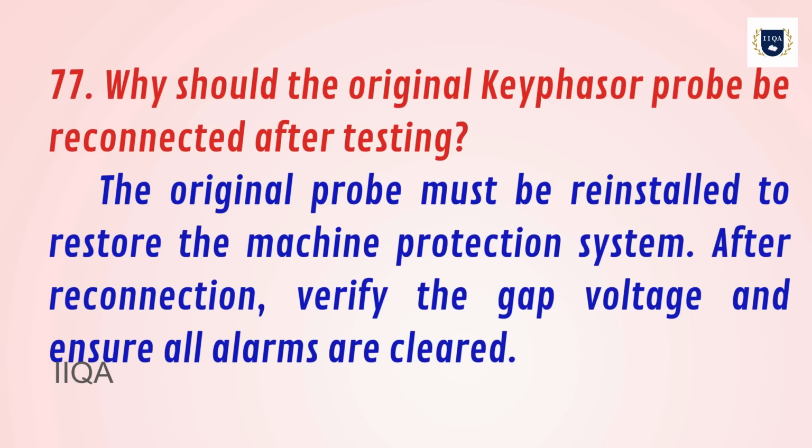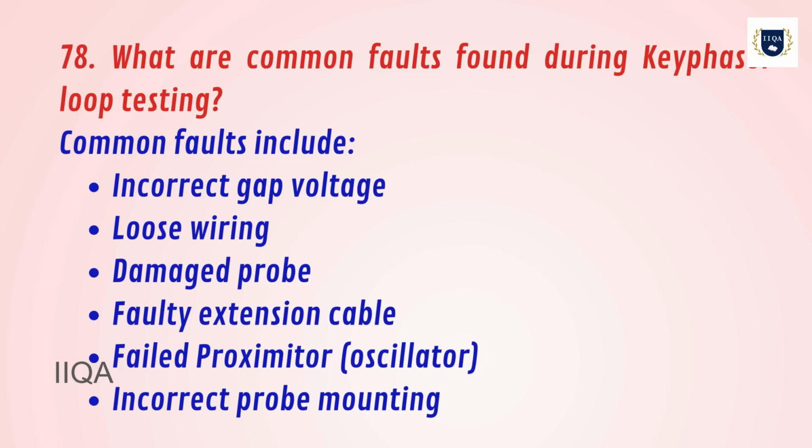77. Why should the original Keyphasor probe be reconnected after testing? The original probe must be reinstalled to restore the machine protection system. After reconnection, verify the gap voltage and ensure all alarms are cleared.